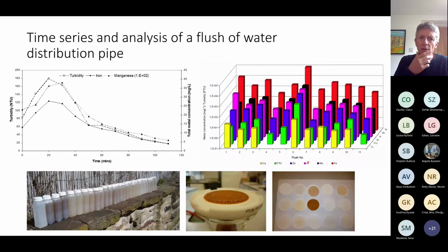So I showed you an image earlier of a hydrant being opened and dislodging some material. That's a very common way for us to look at and understand what material is built up inside pipes. Because they're buried underground, under our roads, actually digging them up and accessing the pipe is a real challenge. So the easiest way is to open a fire hydrant, create some more aggressive hydraulic forces in the pipes than normally used, and observe the material that you mobilize.